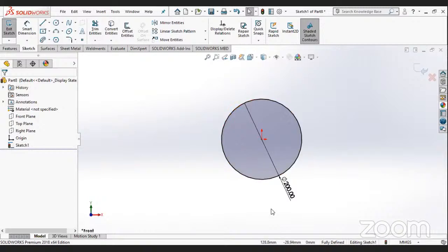After making this, we'll see what the height of it is to extrude. You can see here one height is given 124 and one is 130. So minusing this, the upper part which is coming up here is your 6 mm height.